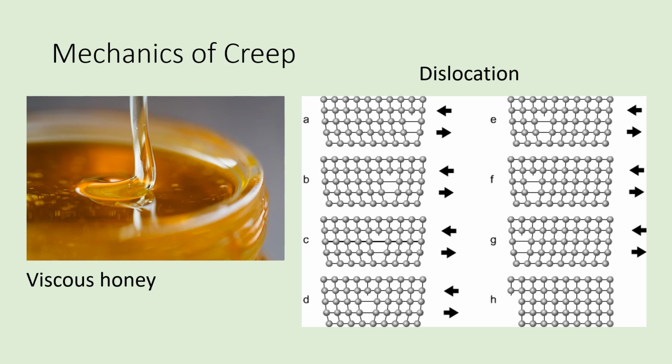The physical mechanisms causing creep differ between the classes of materials being examined. Even within a material, the mechanism that causes creep can change with both stress and temperature. Viscous creep is based on the idea that some nominally solid materials behave in a manner similar to a liquid with very high viscosities.